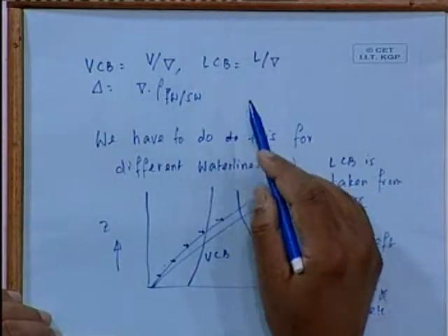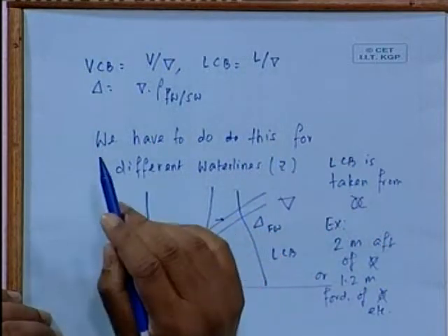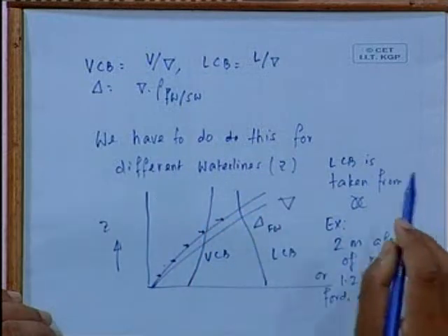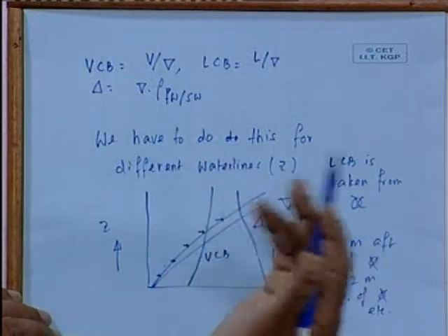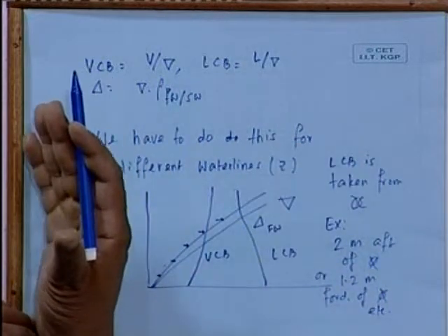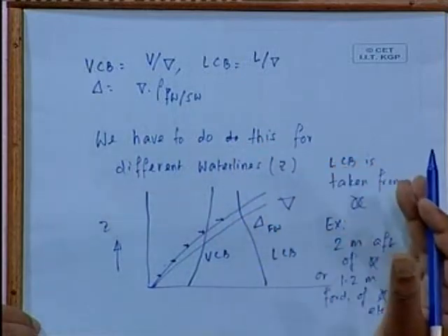In the previous one where I took moment, you could take n to be 0 for AP and 1, 2, 3, 4, or you can make midship 0 and n going negative towards AP: -5, -4, -3, etc. and +1, +2. Or you can calculate from AP and simply subtract L by 2.